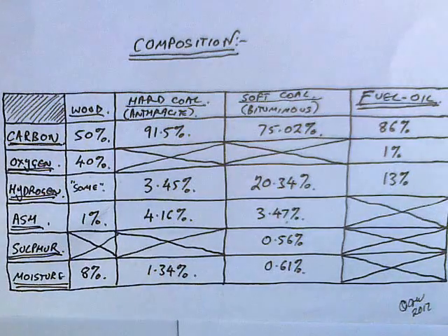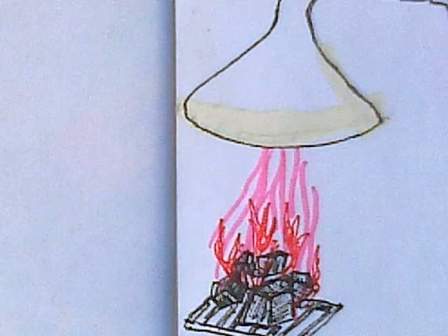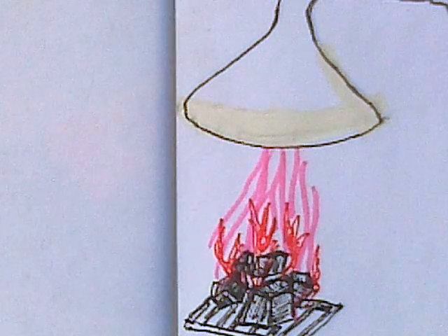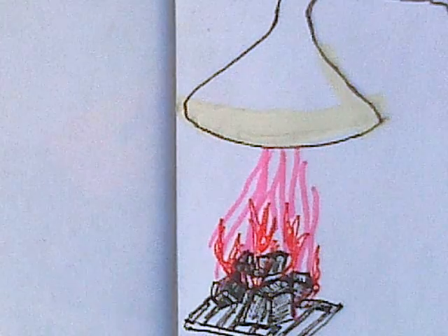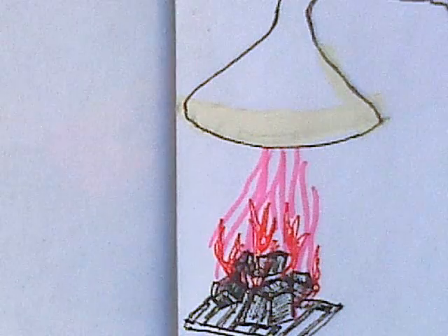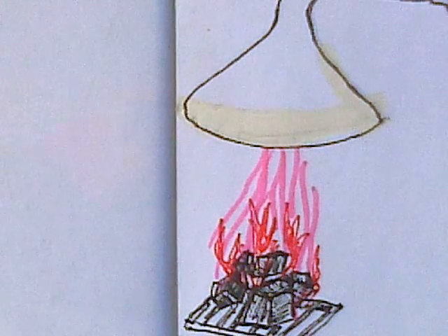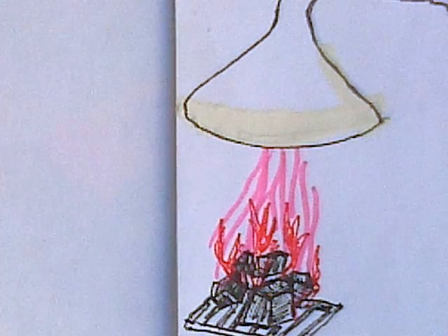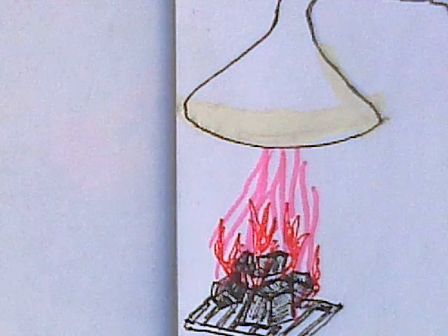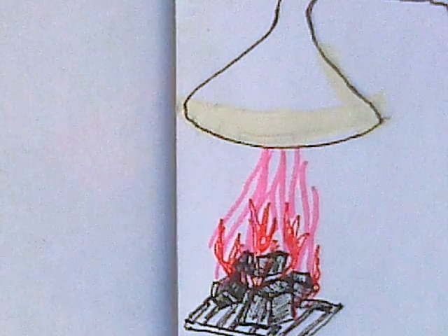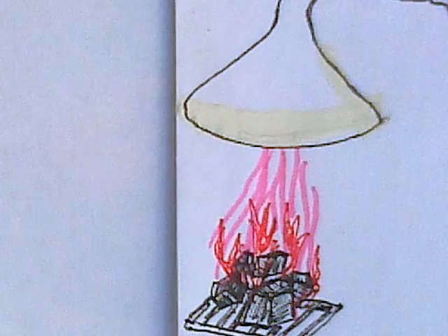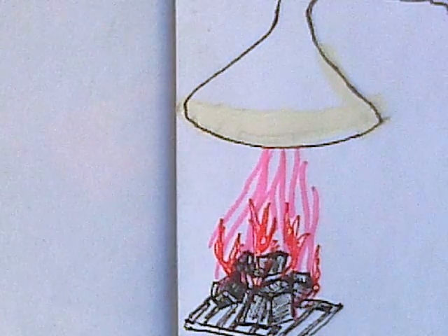The simple fact that there's between 75% and 91% carbon in the coal means that you're going to make a huge amount of carbon dioxide when you burn it. Now, whereas you can burn LP gas and run the hot gas in a turbine to convert the gas heat energy directly into rotational torque, you can't do that with coal because the ash content we talked about earlier will literally sand the blades away. So you have to do something else with the energy that comes off the burning coal.